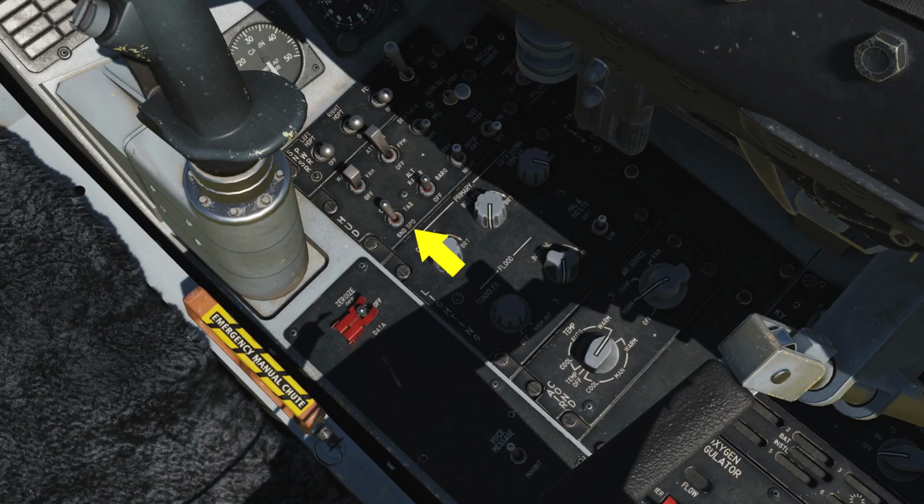The airspeed switch allows the airspeed to display as calibrated airspeed, true airspeed, or ground speed. The altimeter switch allows the altitude tape to indicate radar altitude, barometric altitude, or automatic. When set to automatic, radar altitude is displayed when the height above ground is less than 1,500 feet, and barometric altitude is shown when above. The HUD brightness switch has default settings for day and night, and an auto brightness function that will adjust accordingly.